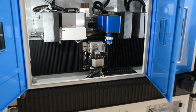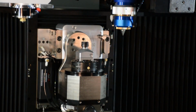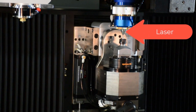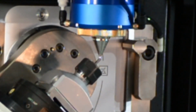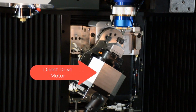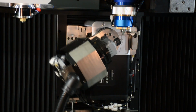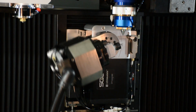Here's an example of a machine that takes advantage of direct drive motor technology. The laser engraves very small features onto a very small part, which is rotated precisely and rapidly by a direct drive motor. The whole assembly must be small because it is suspended on an arm which also rotates. Compact design with high accuracy and low vibration makes the direct drive motor a superior choice over gear or belt transmissions.